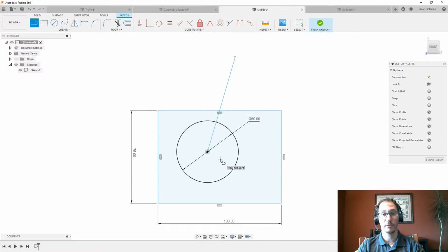And by the way, for all of you that are on the keyboard with Brad right now, this is the same method that I've seen Brad use quite a few times as well. If you draw your line and you draw too close to horizontal, it'll automatically add the constraint for you. But if you want to make sure that you're more deliberate about putting in that constraint yourself, then intentionally draw your line a little bit crooked like I am. And then you could apply that constraint and be confident that it's the exact constraint you want. So let's go and apply our constraints.